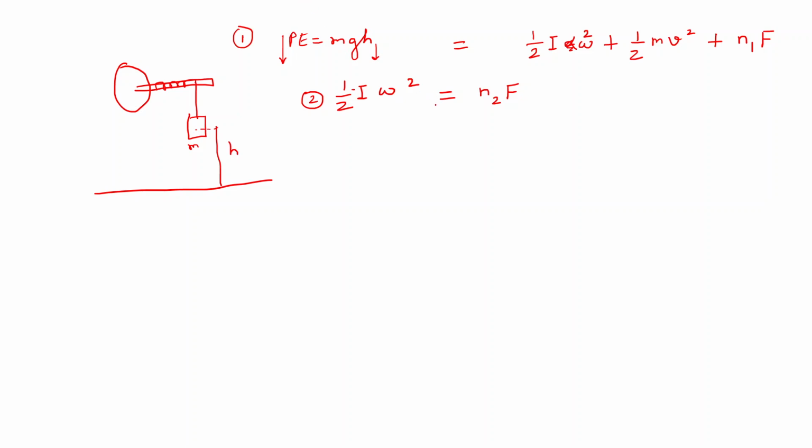From equation 1 and 2, I'm not going to derive it because the professor has already done this, as you have seen in the lecture. What I just want to tell is, this is the basis for getting the working formula. From these equations 1 and 2, we find that the moment of inertia is I equal to m 2gh omega divided by omega square, minus r square, divided by 1 plus n1 by n2, where omega is 4 pi n2 divided by time.